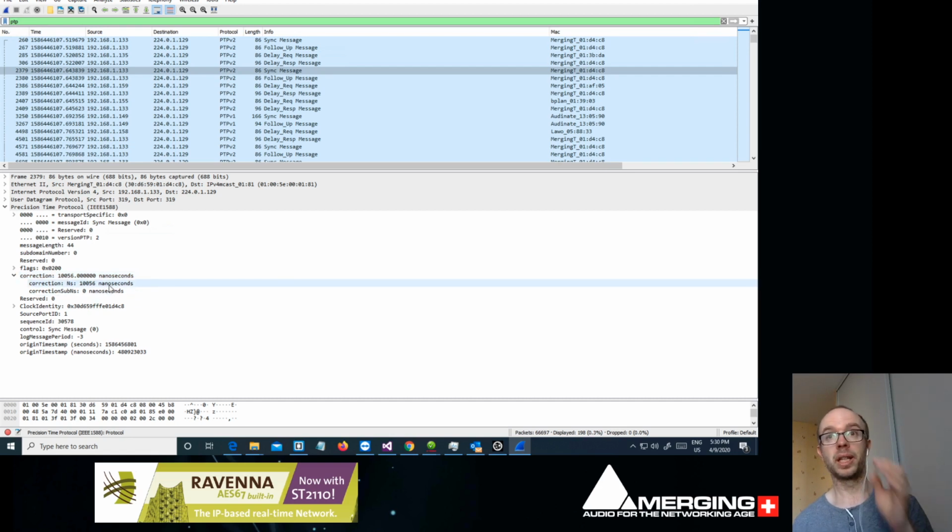And this way we can achieve really great clock accuracy, and it's typically either you have a really well-designed network and you have a lot of money to spend, and then you can have every switch on your network be a PTP switch, or you can have PTP switches at specific points on your network when you really need your PTP clock to be cleaned.